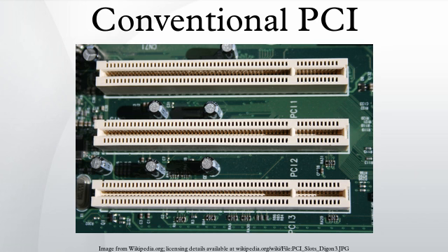Conventional hardware specifications. These specifications represent the most common version of PCI used in normal PCs: 33.33 MHz clock with synchronous transfers, peak transfer rate of 133 MB per second for 32-bit bus width, 32 or 64-bit memory address space, 32-bit I/O port space, 256-byte configuration space, 5-volt signaling, reflected wave switching.